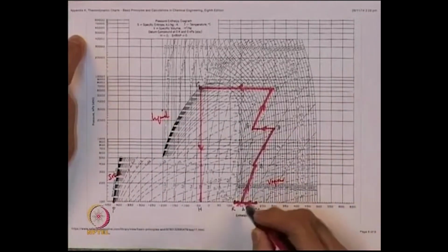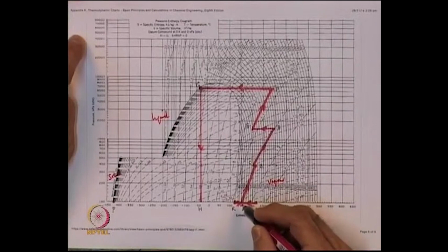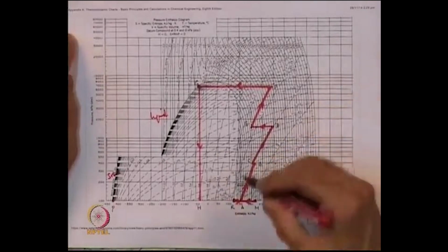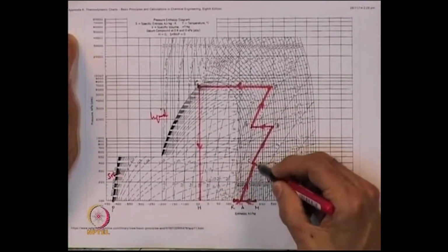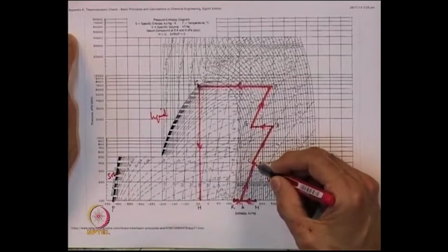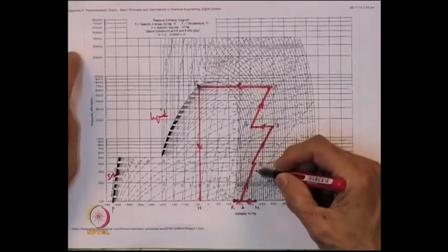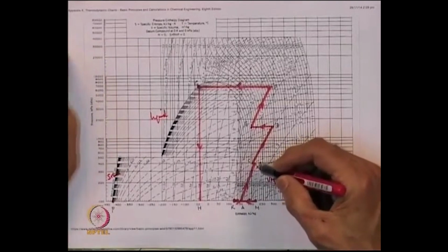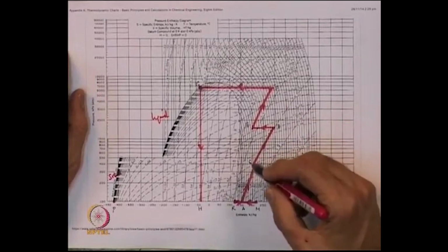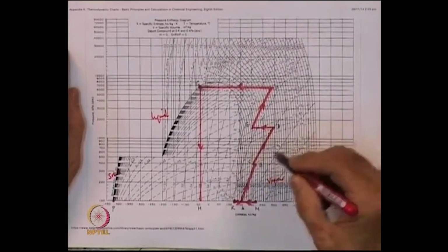The process, let us say we start with 1 kg at the point A, which is actually a mix of 2 things. What we have is an isentropic compression. I follow the line of constant entropy up to 400 kPa, then you cool it down to C, which happens to be at 25 degrees, because your coolant is available at 20 and you have to maintain a 5 degree difference between the cool stream leaving the heat exchanger and the coolant entering. So, 25 degrees is all that you can cool to.